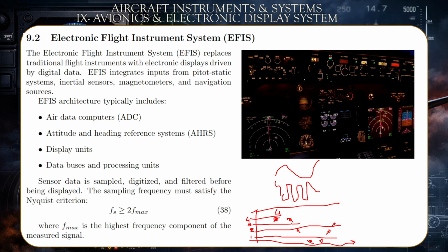If it's closer to 3, it is snapped to 3, etc. Then for each quantized level, you have a different binary code. Let's say at 1 you have 001, at 2 010, at 3 011, and at 4 100.